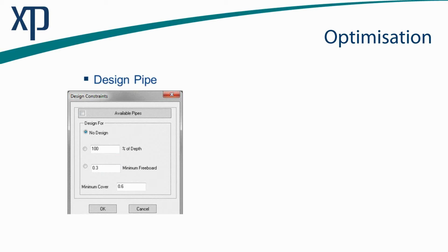Another very important part too is cover, and the design of any simple sewage infrastructure set does also relate to stormwater, and that is clashes. Other elements that we need to ensure that we don't clash with sewer design are things like telecommunications infrastructure, stormwater, water supply, and at times, sewerage is usually the one that dictates most of those other characteristics, simply so that we can address the localized grade requirements of your network.